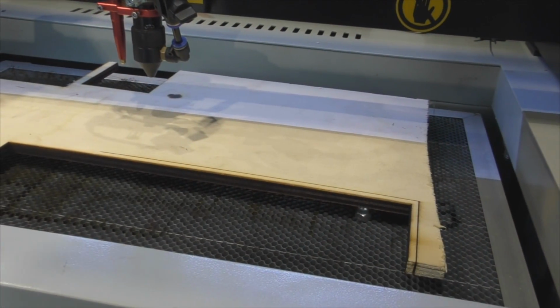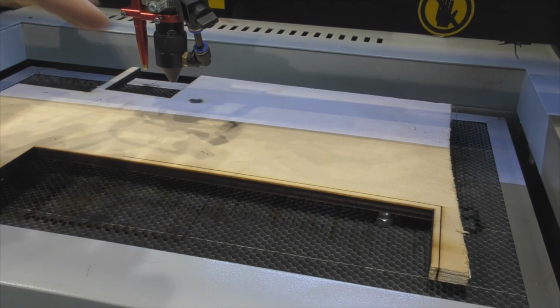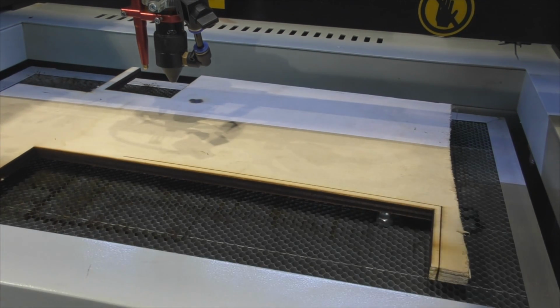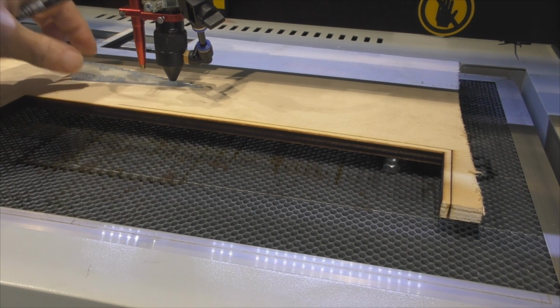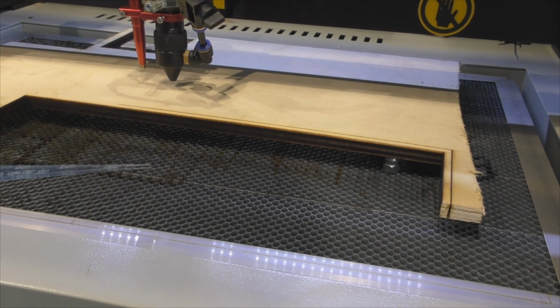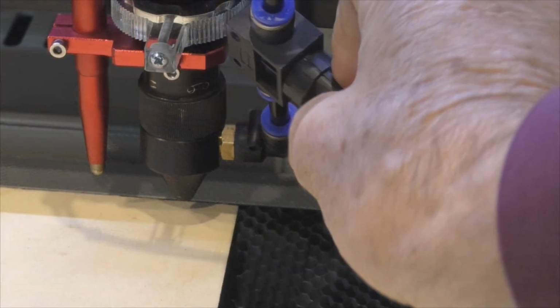Now here we've got a piece of 10 millimeter plywood, and we're going to try, first of all, with this 2.5 inch lens. We'll work the other way around this time because we happen to have the 2.5 inch lens in. So the ideal situation would be to have 5.5 millimeter gap. We're going to start this test off somewhere in the middle. Let's just say 10 millimeters a second. We've got full power on again. We're going to turn the air assist on,